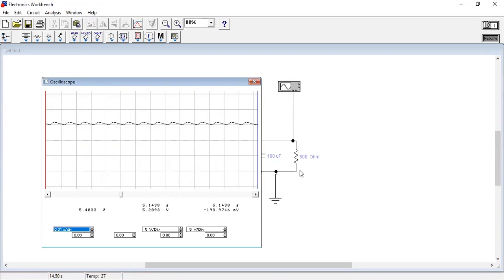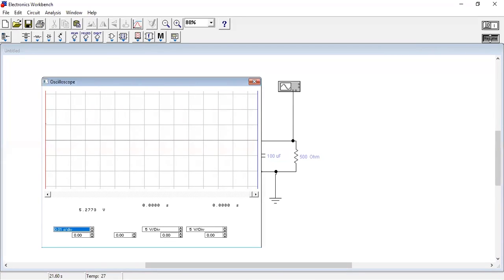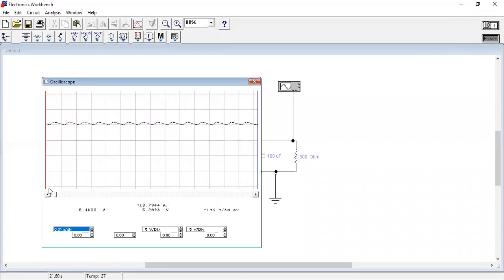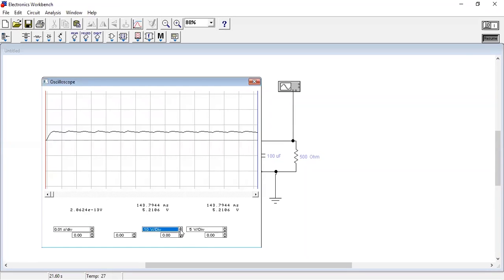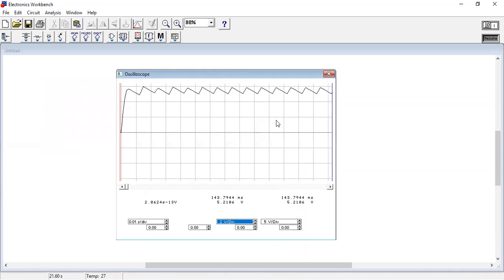You want to measure the output waveform delta V, you can see in the procedure, that's delta V, and you can change the XY position and find the value. Here one box belongs to 2 volts, so you can change it in your software.